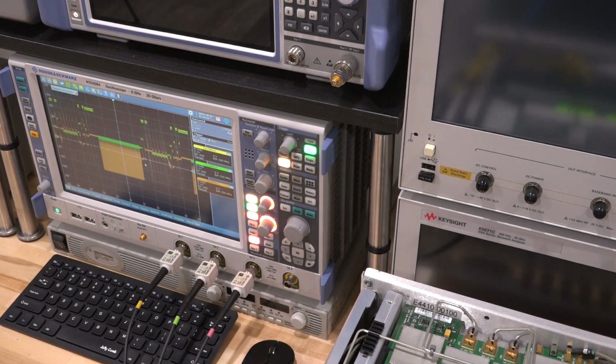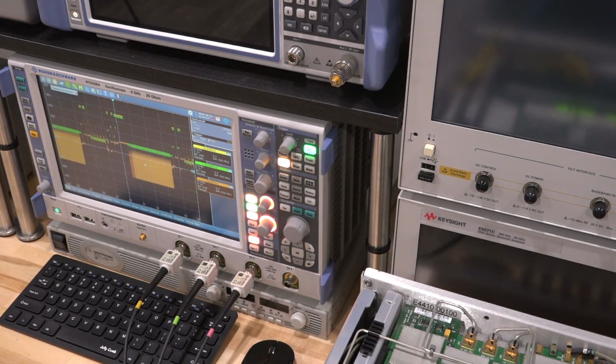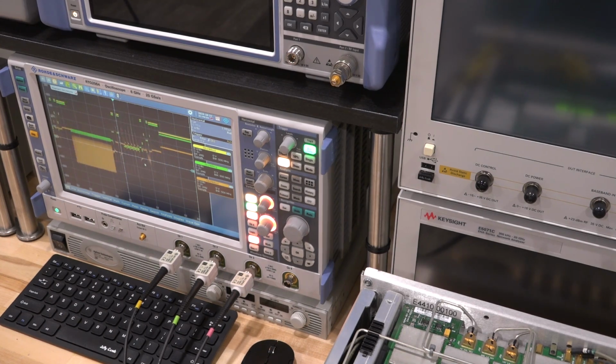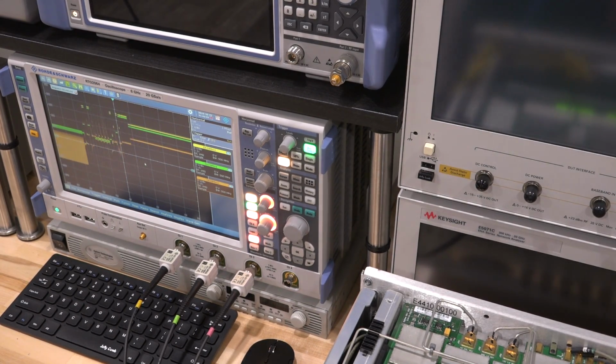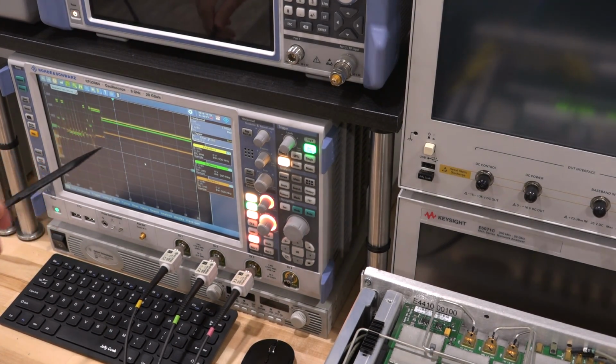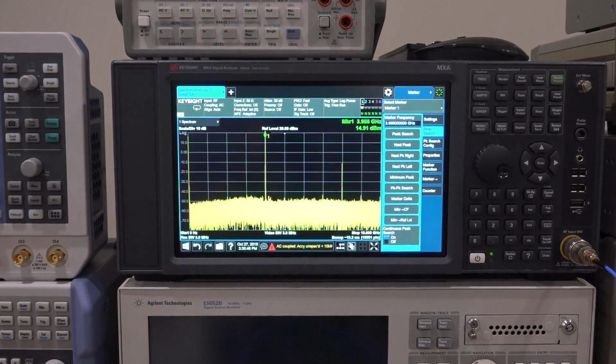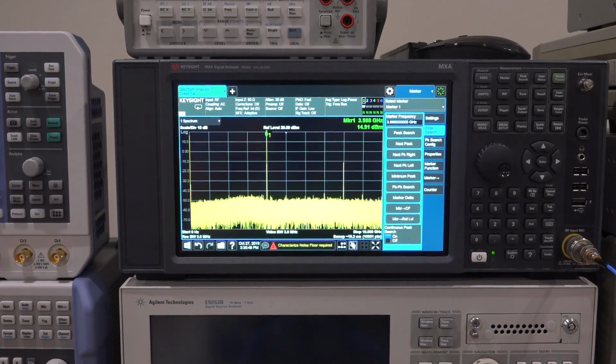So let's go back down to a frequency where a lock does happen. Let's go back to 3.65 gigahertz where we know it works. There you go. It should eventually stabilize. See, it stabilizes because it searches for a while. Eventually it finds. This is multiple loops at the same time. There are some analog loops, there are some digital loops, but you can see that the voltages have stabilized. So indeed the frequency is locked again. And if I go all the way up here, you can see that it is stable once again where it should be. Well, let's do a couple of experiments.